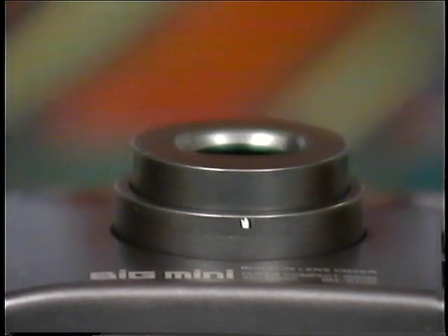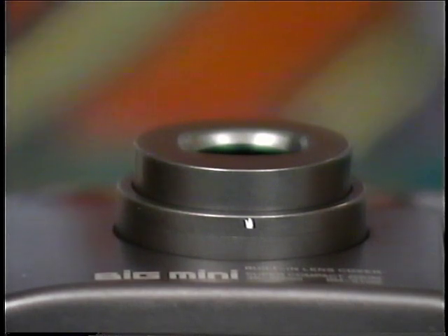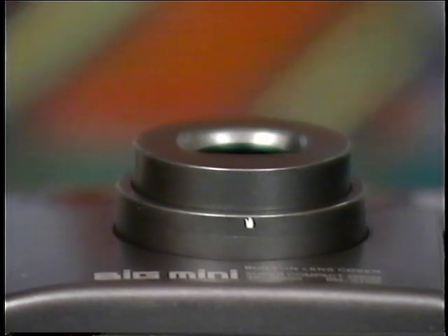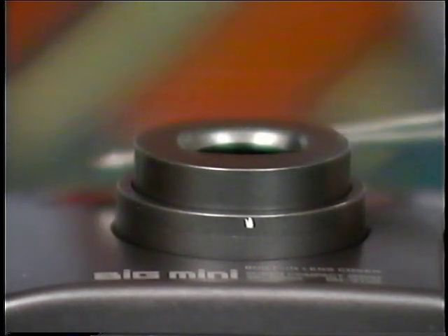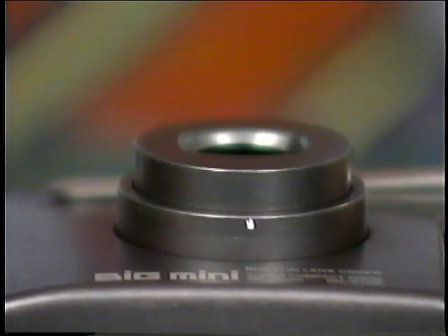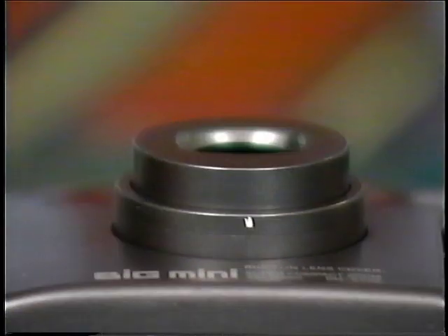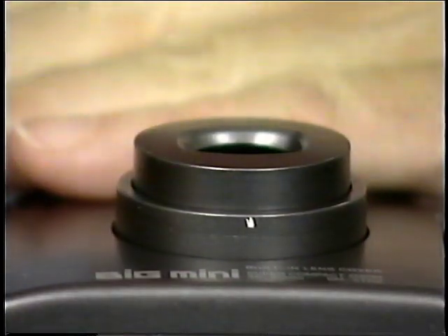And if you check the focus straight above the camera, say from 3.5 to 4 feet away, when pressing the release button, you can see how far the lens turns to focus. In other words, it should focus out to achieve the close focus. Next, I'm going to use my tweezer tips, you can use your finger, and what we want you to do is cover the rangefinder. In other words, the two windows at the top, I can cover those with my hand.